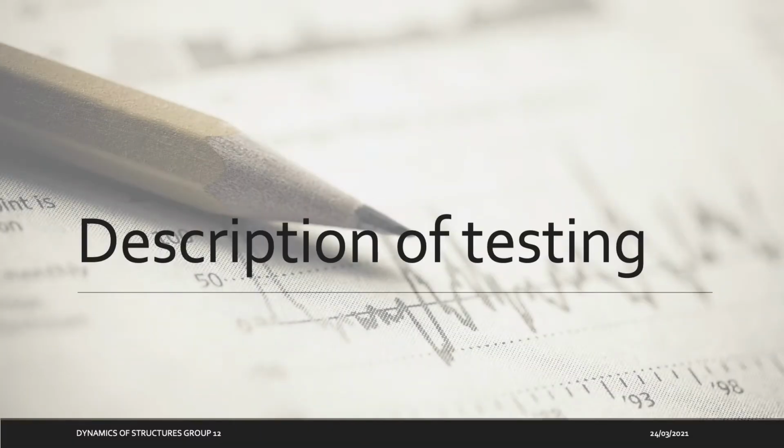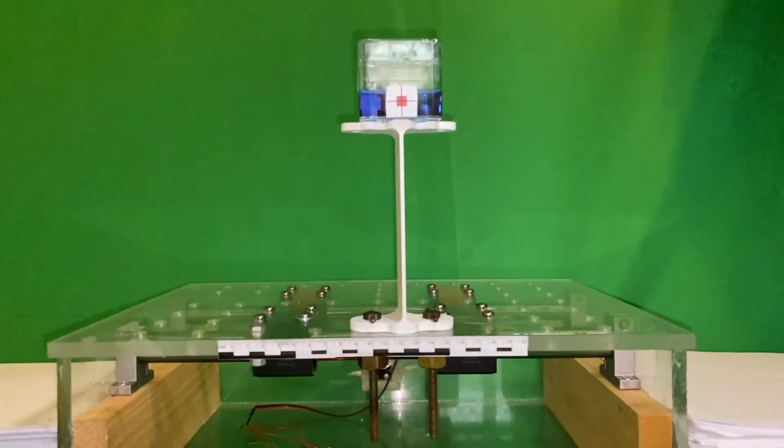This experiment constituted a model structure that was subjected to an almost harmonic base motion provided by a shaking table at a dominant frequency of 3.5 Hz. The resultant motion of the structure was recorded using the phone camera at a frame rate of 240 frames per second. This was deemed sufficient for the experiment as the resultant frequency of motion of the structure was not a multiple of this frame rate and was smaller than the frame rate of the camera.